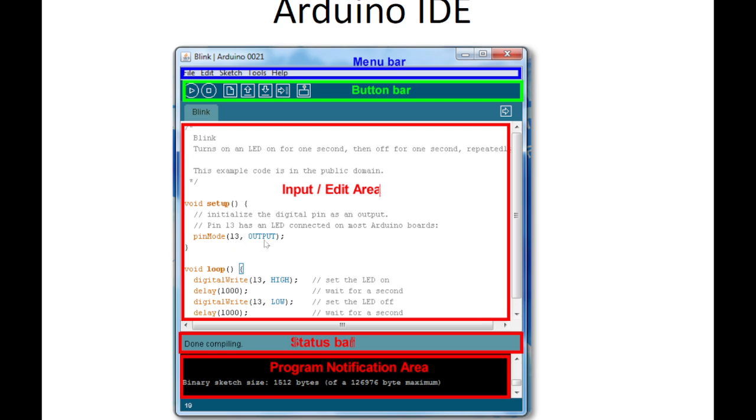So primarily what it's doing is making that particular bit 1 or 0. Most commonly 0 means it's an output, 1 means it's an input. So this statement is setting up the registers for the Arduino board. A very important point to understand and be very, very clear on. Okay, that's how easy it is to set up registers if you're using Arduino.